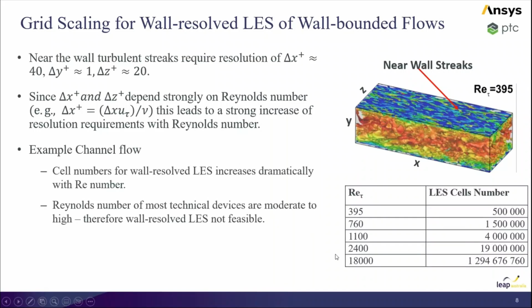So all I want to show you here is that if you choose a Reynolds number based essentially on the friction velocity here, then as this starts to go up a bit, the requirement of cell size, number of cells to integrate to the wall, explodes and becomes completely and totally impractical. So you can see immediately why we just don't recommend this. And the big issue is a lot of people using LES don't realize this.